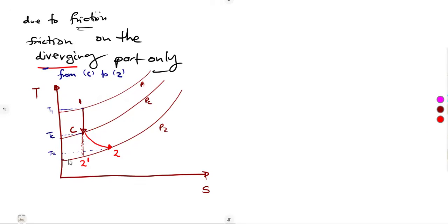And here it's going to be T2. And in terms of the temperature at this point, we're going to have T2 bar, which means there are now 2 temperatures at 2. At this 2, there are now 2 temperatures, an absolute, actual, polytropic value, and an adiabatic, ideal value.